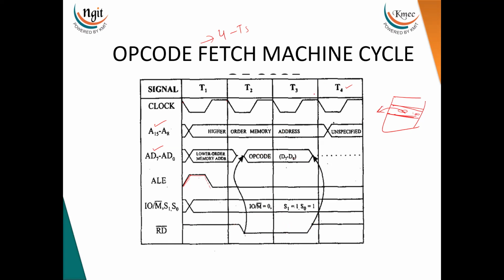Now this is for only 3 clock cycles. The address is available up to 3 clock cycles and the data is also available up to 3 clock cycles. After that you can see the dotted lines. This is called logic high and this is called logic low. If it is in between, it is called the high impedance mode, which is neither logic 0 nor logic 1.